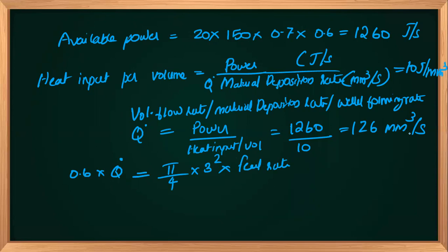So here the same it is there, right? So these are equal. The 60% of the weldment is formed by the deposition of the wire, means that whatever deposition rate we have found out, multiplied by 0.6, will give you the wire melting rate. You can say that feed rate multiplied by your area. So if I want to calculate the feed rate, directly we will get it from here. Or this is nothing but your material deposition rate, which is area into velocity, because the velocity is given. You can find out the area, and again you will end up in the same formula. But it will be easy from here, right?